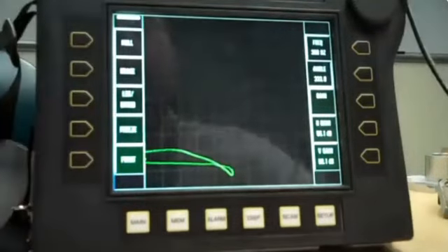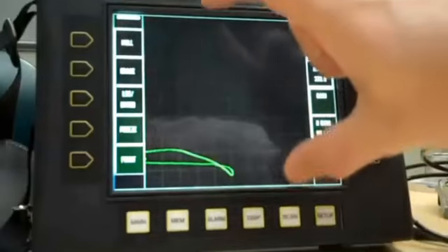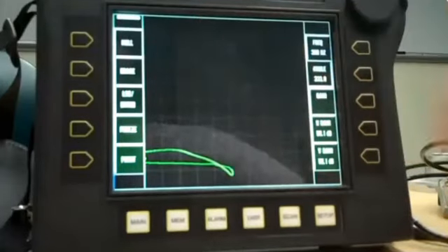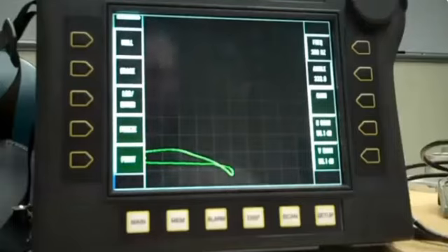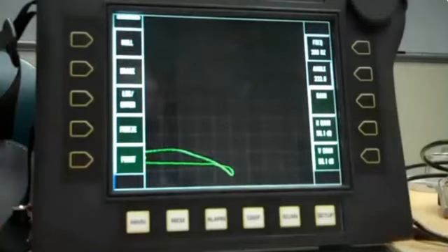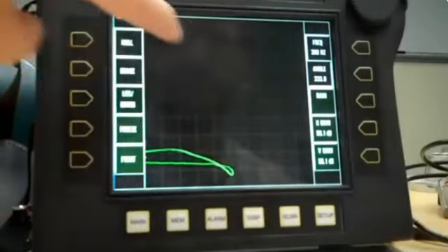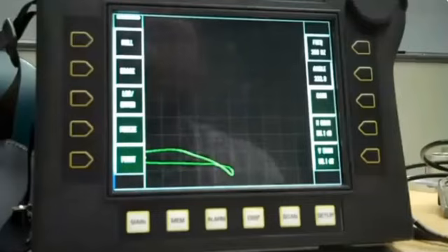Whereas when we raised the frequency up to around 3 kilohertz, we saw a nice big spread for all those different thicknesses, because we were pretty much set for that standard depth of penetration. So, just something to think about when you're testing your frequency and what that does with your conductivity curve or your thickness line. This is a common application, testing for material thinning on the backside of a piece, where you can't see the top, maybe it's corroding from the backside. You just know that the thinning line is going to come up like this, so any point on there tells you that the material has gotten thinner, and I've lost conductivity.